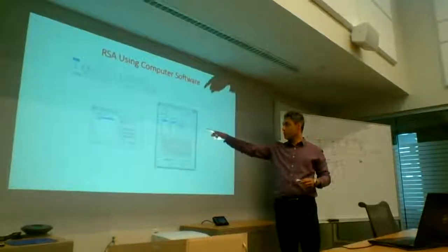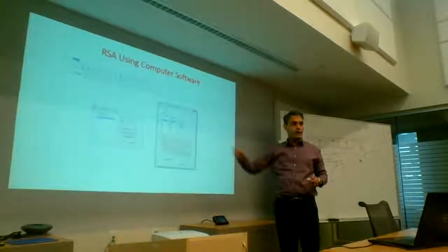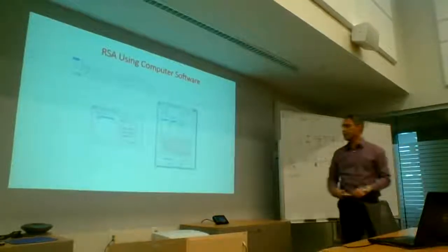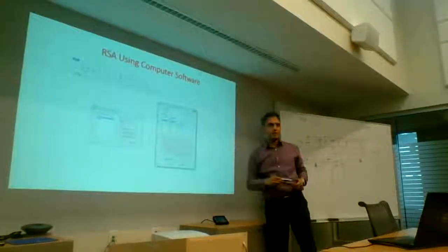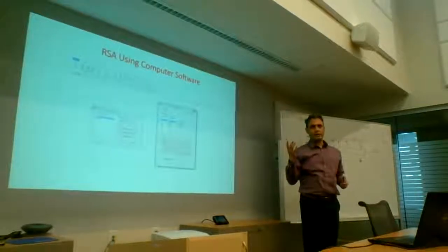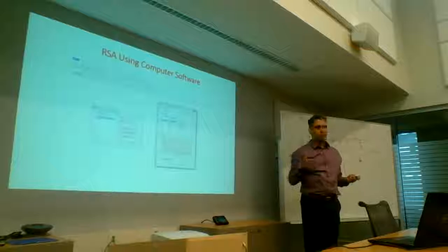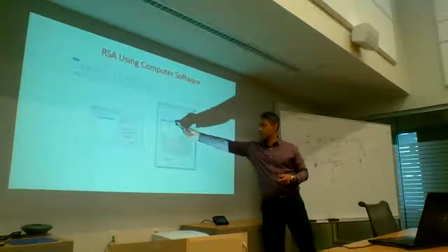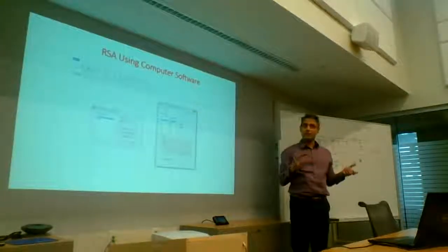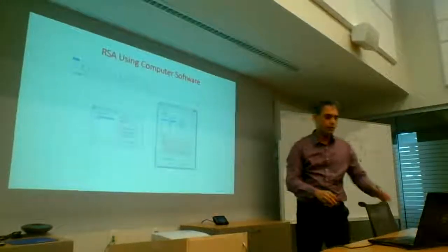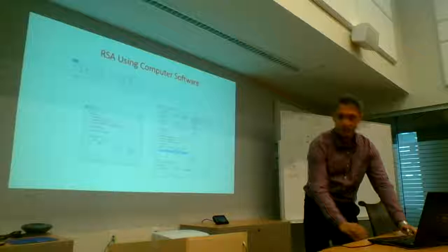But if you put this into the program and you see almost no load in your structure, you know that you've put in 0.61 meters per second squared, divided by 9.81, which is not even 10% of G. Okay, so if your intention is that this is 0.6 G, you expect to see a fair bit of load in your system. Just make sure that you've set up your load case and your load combinations properly.